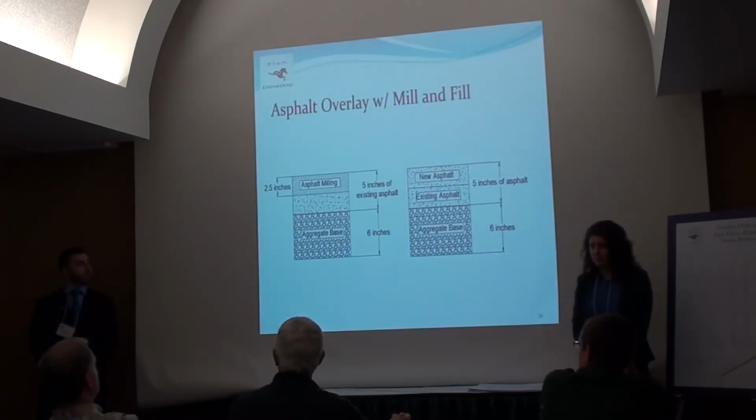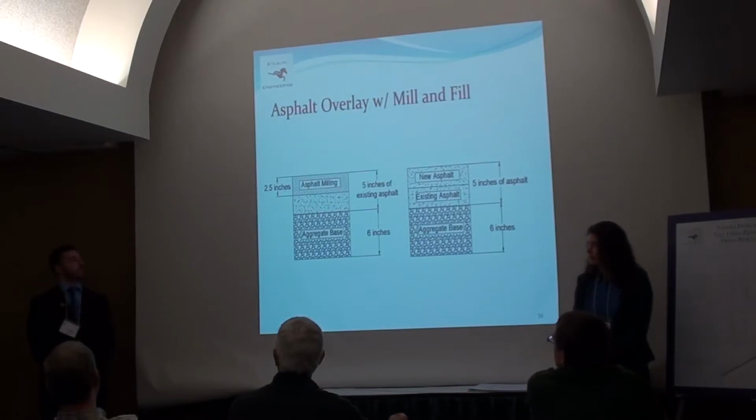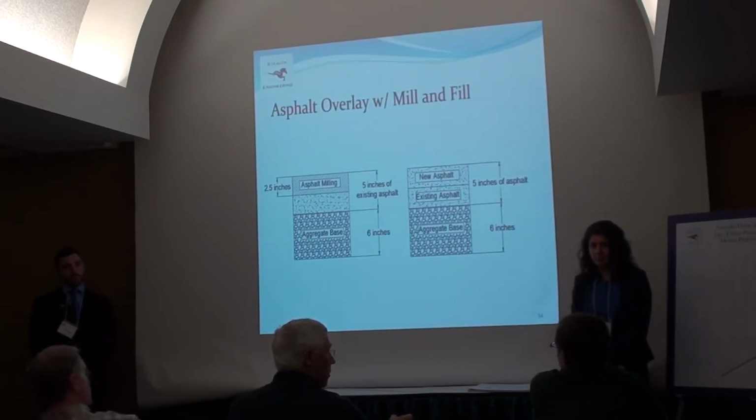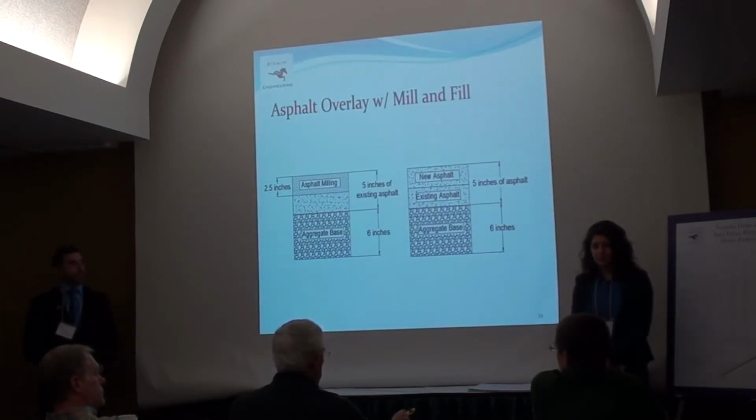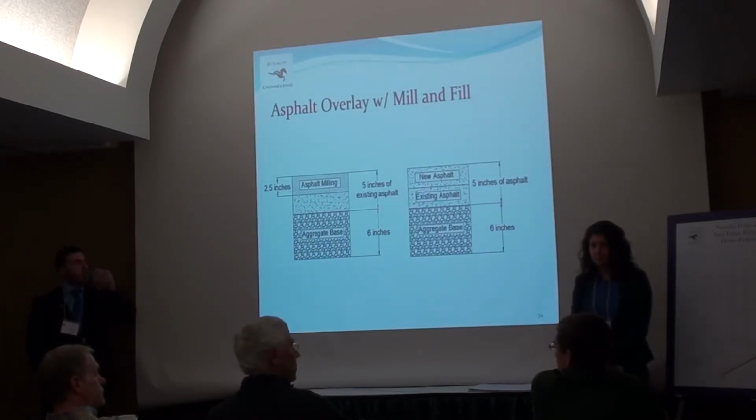I don't have the pavement cores to tell you how deep the top-down cracks go, but just estimating on observations, that's what I assume. It's only a couple-year-old road, so we hope they're not that deep. I want to take some cores and see if we can go less and reduce the amount of work in dollars there.